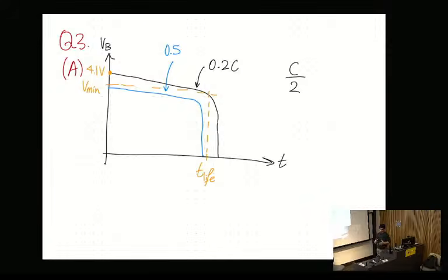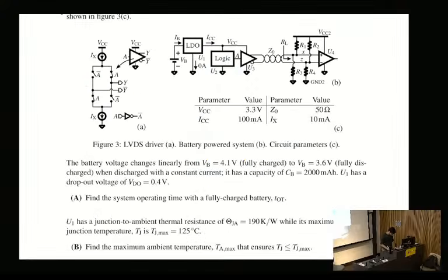When you're building protection circuitry for charging, fundamentally what you're doing is limiting the charging rate. So you calculate how much current you're expecting to get out of it, and then you have a module in your circuit which limits it to that number. So it only pulls that amount of current for charging. Otherwise, you'll blow up your battery. Cool. So then that's the context of that.